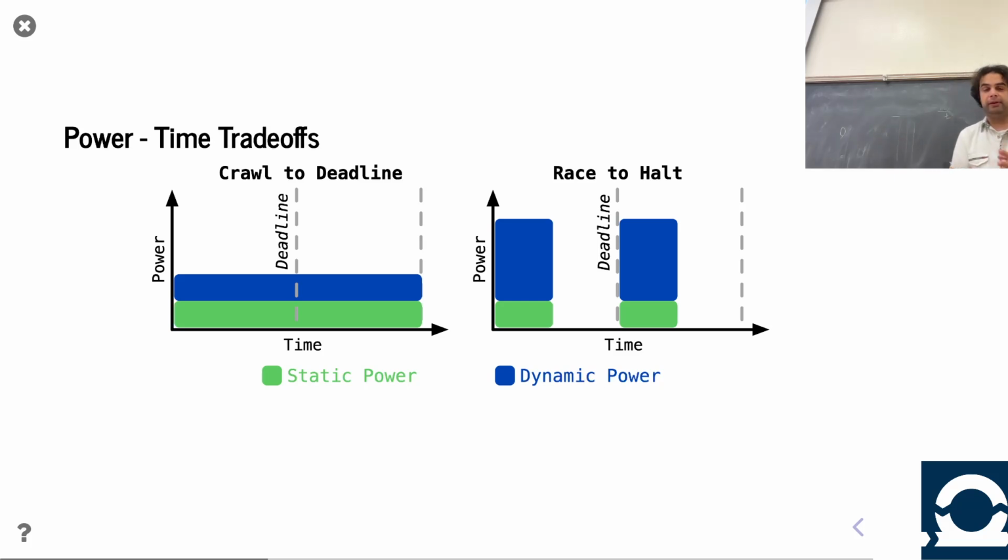So when it comes to, as an architect, managing the power, you have some choices, right? Let's say you know what you need to do. Like I want to play this video on my phone at 60 frames per second. So okay, I need to decode a frame of video, get that information to the frame buffer to go into the display, and I know I need to do a frame every 15 milliseconds, whatever it is for my frame rate. So I have a task and a timeline that needs to occur. Now, if you're trying to do that in the most energy efficient way in order to maximize battery life, there's multiple strategies. And depending on your situation, a different strategy may be the most effective.